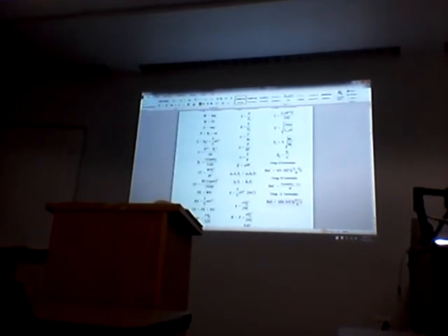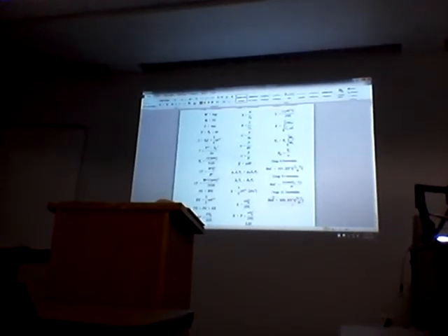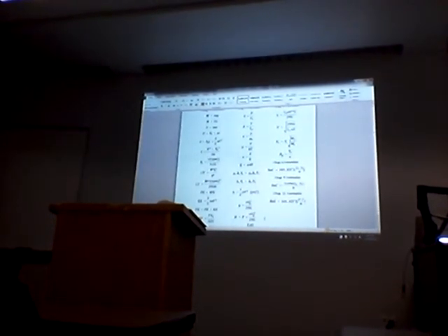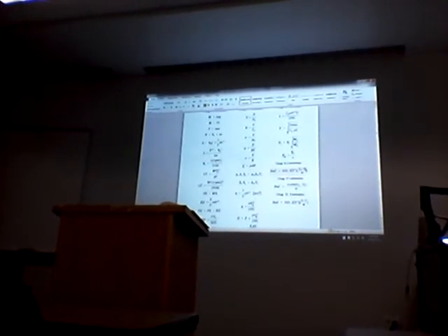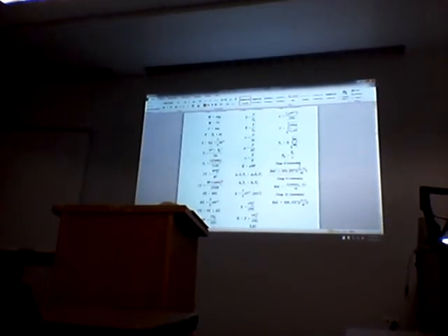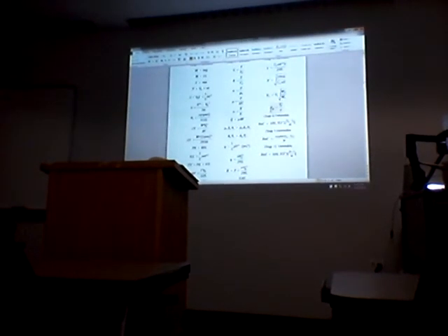And the rate of sink, notice the only difference here is it's basically this in reverse, but what is the drag and thrust? If you've got more drag than thrust, you're going to have a rate of sink. But it's basically the same formula as that one there. TA stands for what? Thrust available, and TR, thrust required. That gives you the possible rate of climb.